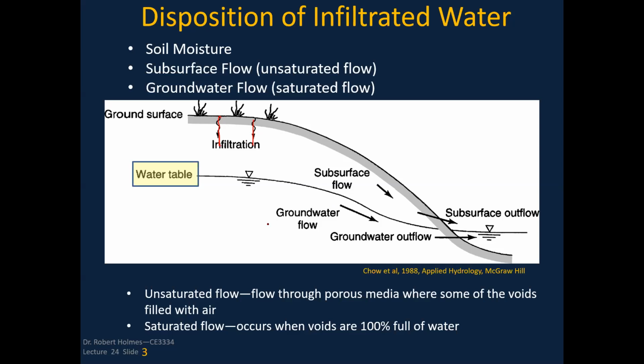Down here, we've got the groundwater table, the groundwater flow. Out here, we've got the stream. When you have this precipitation, it falls, and some of it infiltrates. It will come out as interflow or subsurface flow and end up in the channel. Some of it will go all the way down into the deeper groundwater in the water table. And some of it will obviously run off if the intensity is enough to create excess precipitation or runoff.